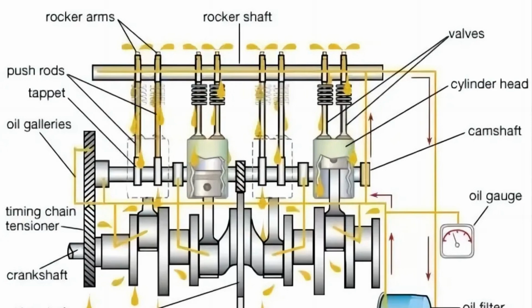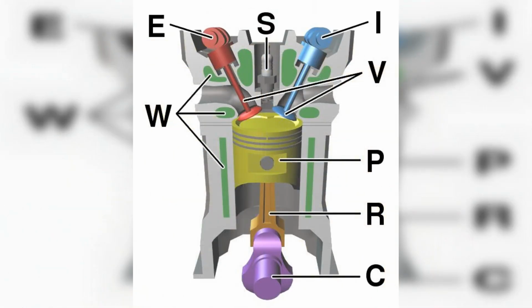Things are even worse when the motor is started at temperatures below 20 degrees of frost. The deficiency of lubrication will be felt until the oil is warmed up to operating parameters, about 90 degrees. So in winter, special techniques should be used to reduce the load on the motor.